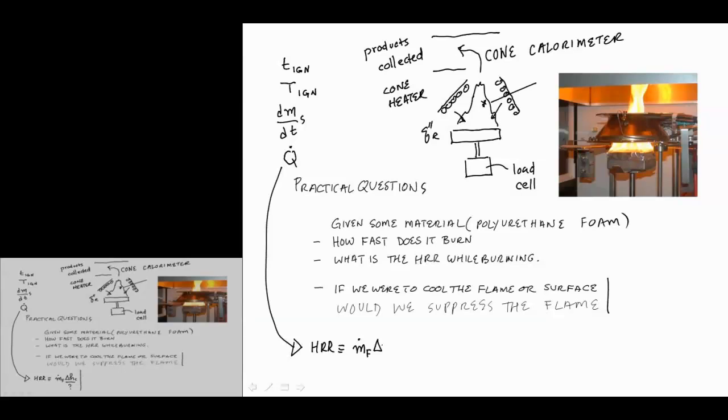Another possibility would be to measure the amount of heating that's done here. So you'd say, well, if I put maybe a thermocouple up here in this gas system, maybe I can just do an energy balance and figure out how much heating was done so that I can back out what the heat release rate is. So basically, conceptually and from a flow perspective, the idea would be that I have a flow of cold air.